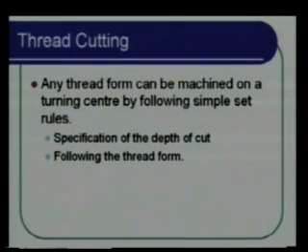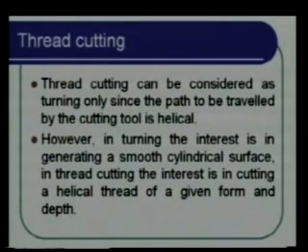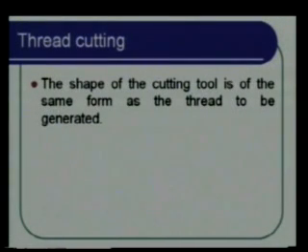Whatever is going to be the depth of cut to be taken, and what is the thread form, that is the actual shape of the thread. Now there are standards available like the ISO standards, so that will tell you exactly how to calculate the maximum depth, etc. So that will be known. And also thread cutting can be considered simply as a turning operation, except that the feed rate that is to be chosen will have to be the same as the lead of the thread that you are going to cut. That's the only important point to remember.